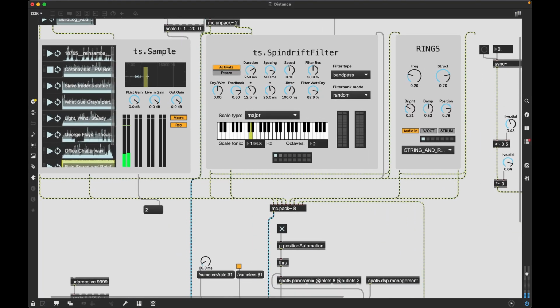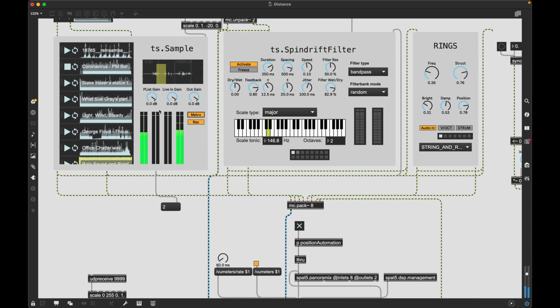Real-time audio capture is one of the main focuses of this system and is integral to incorporating the audience into the work. Using signal from the lavalier mic hidden inside the light, I'm recording real-time input into the sampling module and mixing it with pre-recorded field recordings and effects. The level that the real-time input sits at in the mix is controlled by the proximity value received from the Arduino and is therefore synchronized with the light as it shifts between color palettes.